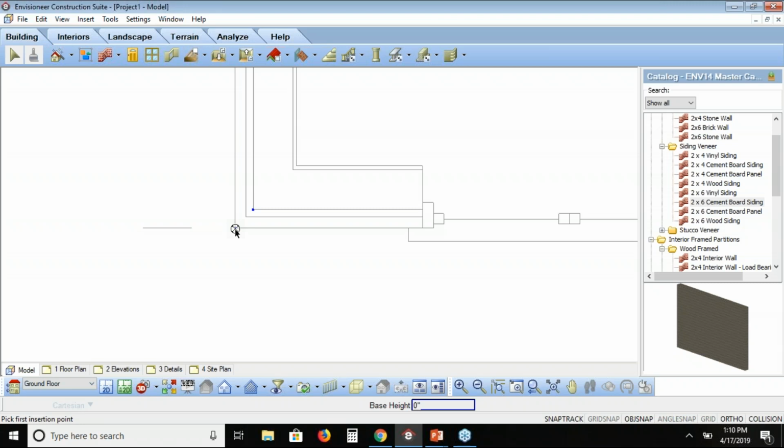If this had remained a raster PDF, the pixelated view, I can't snap to the corners, but I can zoom in and get as close to that edge as possible. So as I'm picking the points for this vector PDF, I'm going to make a choice that's not right on the corner, so I can show you how I can clean that up just as I would if it was a raster PDF instead. So here's the basis of the start of my estimate, this corner right here.